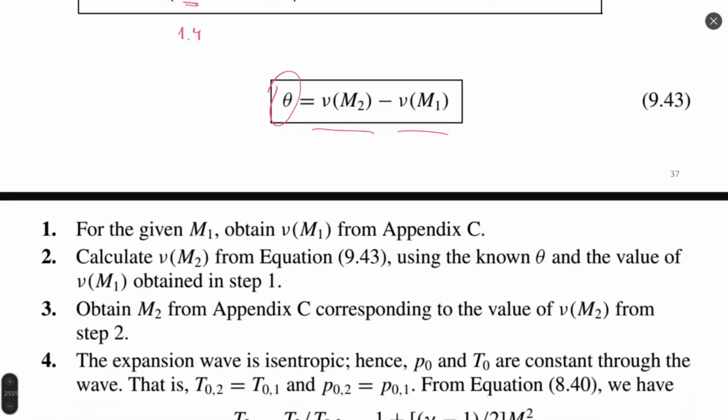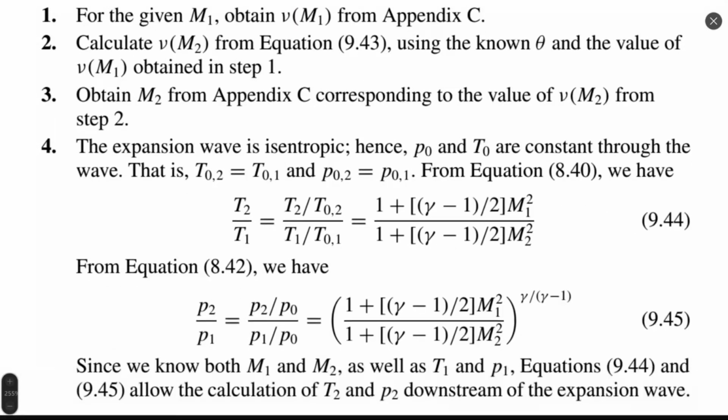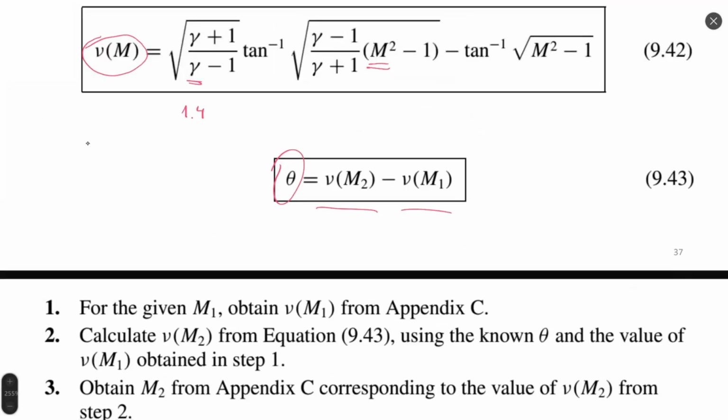I would like to present you also a small algorithm that Anderson gives as an example to calculate any isentropic flow with expansion waves from Prandtl-Meyer. For example, we have flow, and inside such a flow, we know already Mach initial, M1, and we know geometry, which is described by this theta angle. This geometry must expand, so area increases when flow goes in direction.